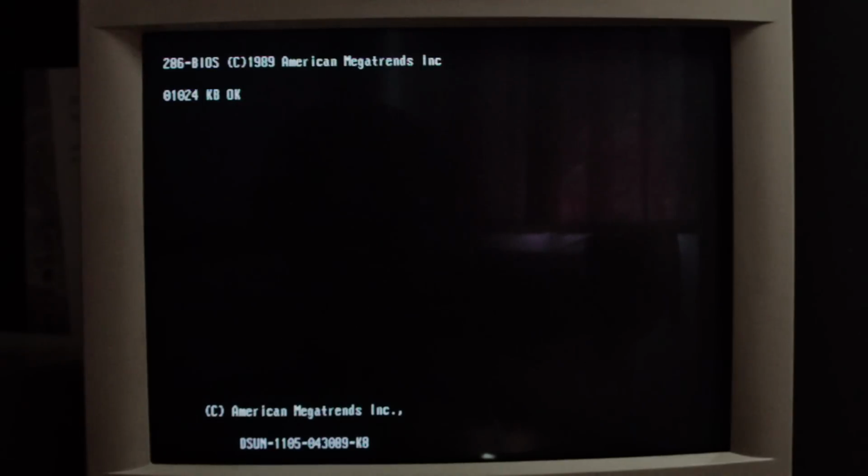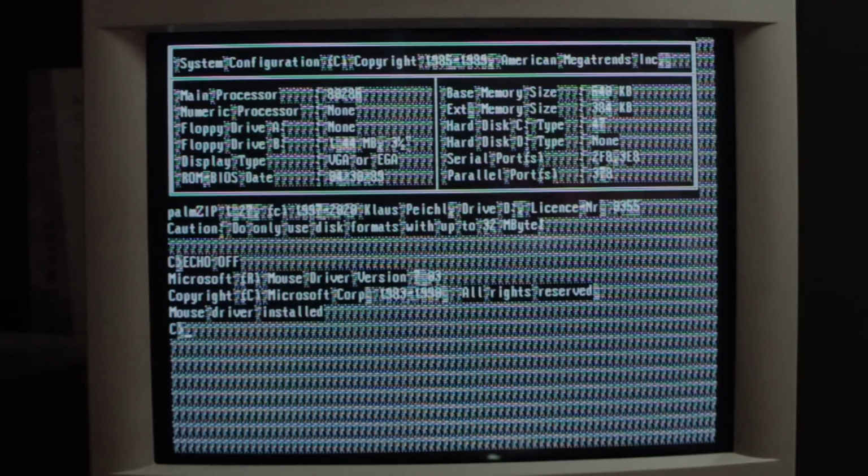Well, I have made some progress, but I wish I could say it was easy. I have actually been having some problems with the card. It hasn't had the issue with the coprocessor overheating that I mentioned earlier, but about every third time that I restart the machine, it hangs like this. We also get a lot of corruption like this, and there's various variations on this, so there's obviously some issues with the hardware itself. But by far the biggest problem is documentation.